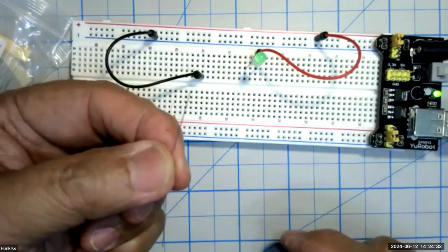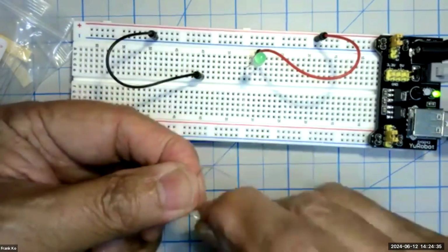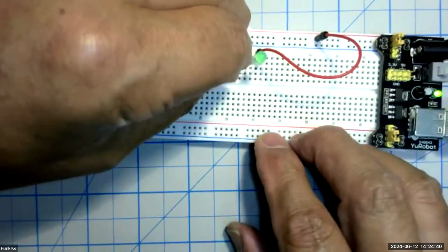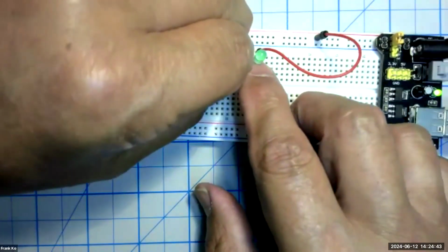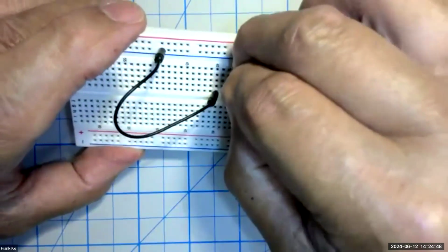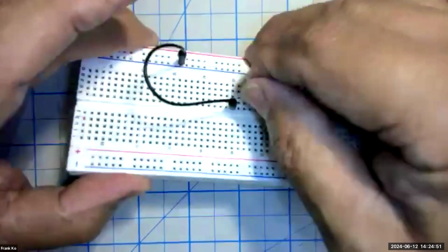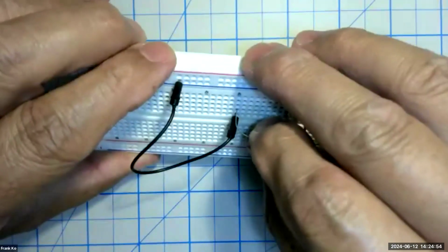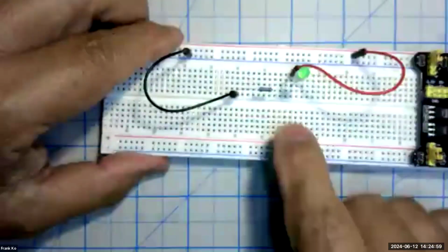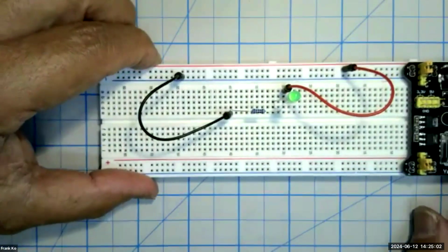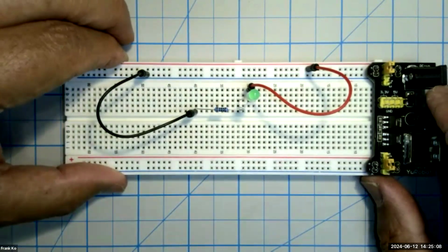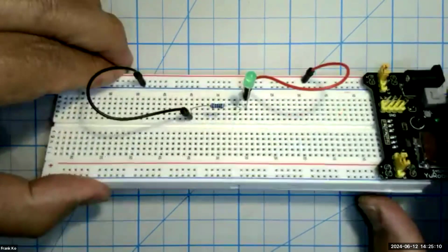Then we're going to grab the resistor and give it a bend, and give this a bend so it looks like the letter C. We're going to very carefully put this in place where the other resistor was. Push this down into 32E and push this down into 40E, like so. Okay, carefully, so as not to bend the leads, make sure that's firmly in place. Feels like it's pretty solid. And touch the button, light it up. Yes, quite a bit dimmer.